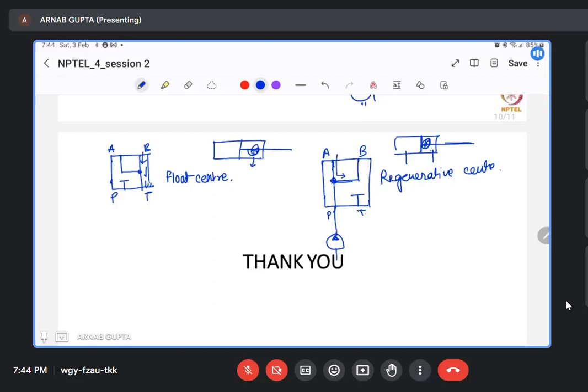Now, since the pump is on here, it will not allow the liquid to come back in this line. It will force it to go towards the B side, like this. So this particular flow will be countered by the flow of the pump. As a result, there will be a regenerative action taking place. This regenerative action is why we name it a regenerative center.